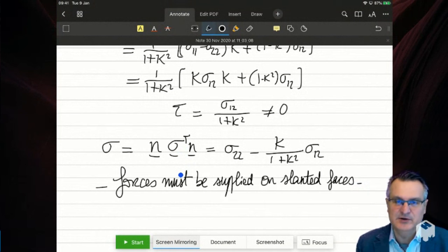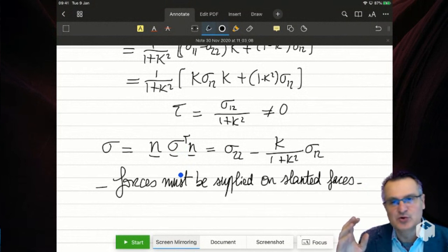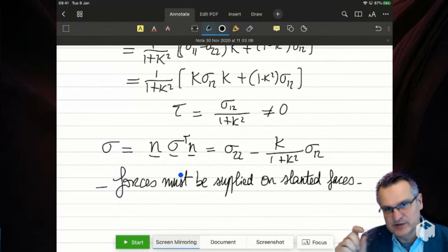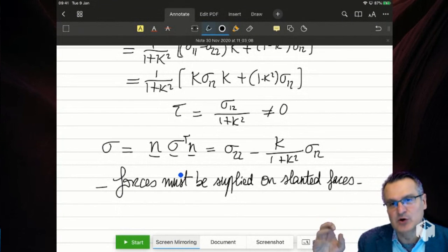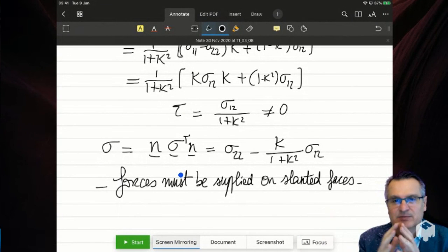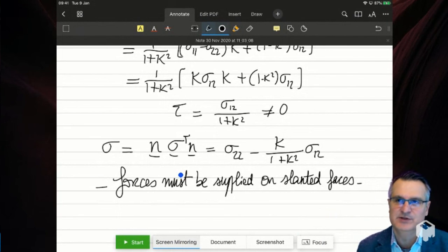So what the protocol standard tells you is to minimize that effect by having a material that's thin, like a rectangle, so that those effects are going to be localized near the edges, and then by and large inside the material it's going to be homogeneous deformation and close to simple shear.